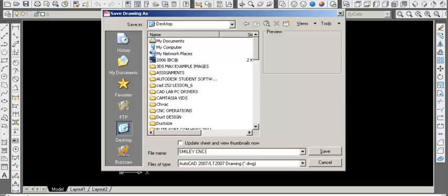We said it was like, what, heck, I don't remember what it was. It was probably 12 by 8 or something like that. If you actually give the size of the plate that you're going to cut from in the name of your file, it helps the operator to know what size of sheet to lay down on there. Since you can't add any information in the file without the CNC freaking out, you can use the file name to do that. You don't have to do that. You can name it whatever you want to, but this is just a tip. And let's say we're cutting it out of a 3/16.